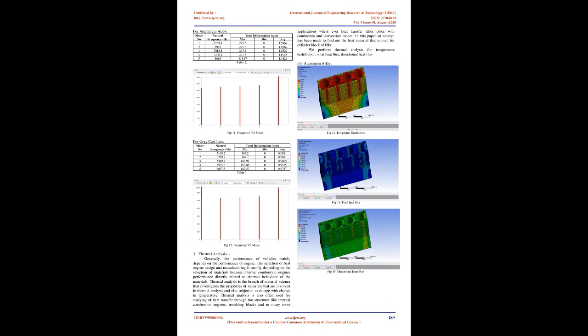1. Static analysis. The basic finite element equation to be solved for structures experiencing static loads can be expressed as K U = P, where K is the stiffness matrix of the structure, an assemblage of individual element stiffness matrices. The vector U is the displacement vector, and P is the vector of loads applied to the structure. The above equation is the equilibrium of external and internal forces.